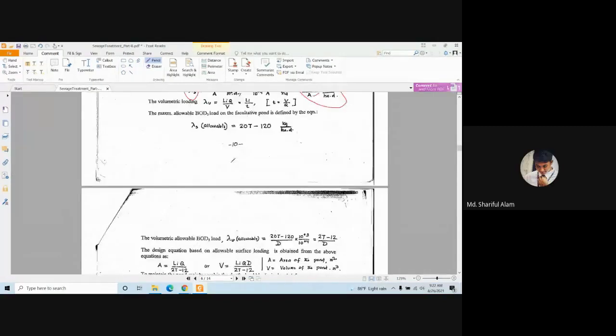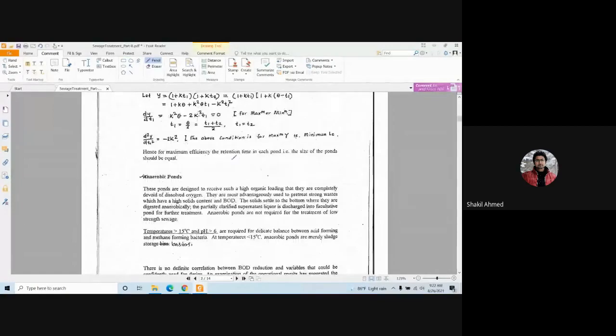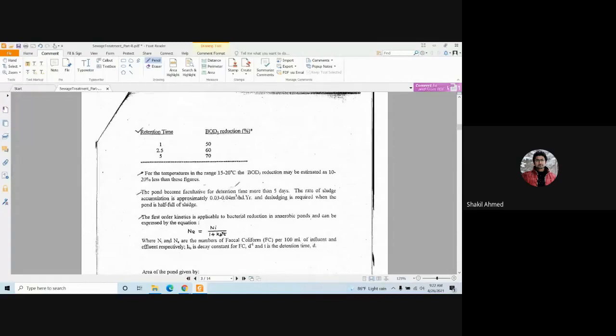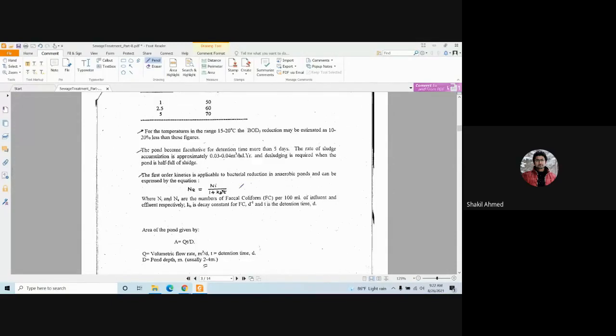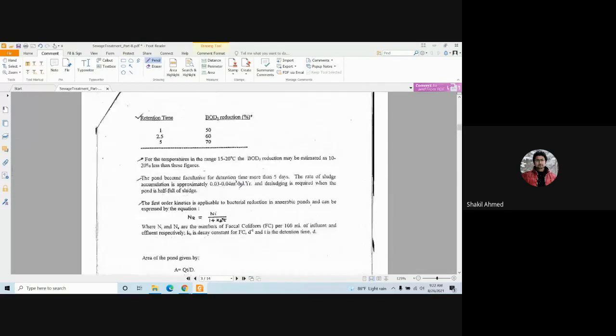Yes, sir. For the anaerobic pond, D can be 3 meter. For the anaerobic pond, T should not be more than 5 days.